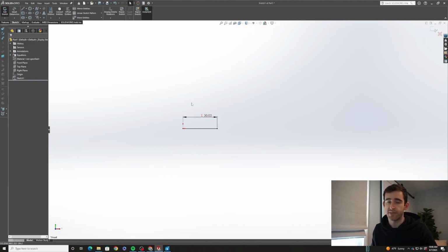And so when I have that list of variables, I can just go into that table and quickly create it. The other time-saving tip I want to talk about is mouse gestures, which you've already seen me use a little bit in the sketch. I'm going to right-click the mouse, and then if I move to the left while holding the right mouse button, I can create a line. If I move down, a rectangle, to the right, a circle, and up, smart dimension.